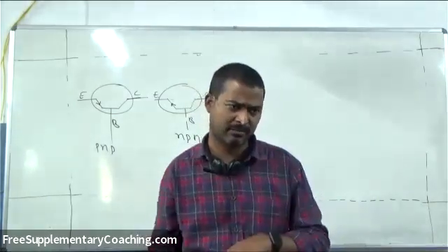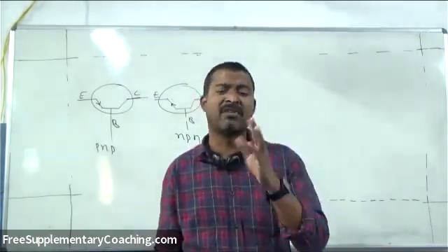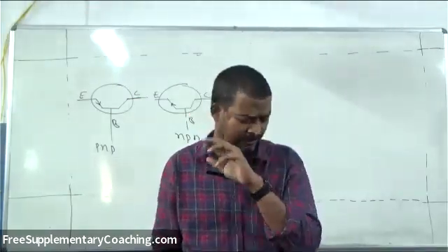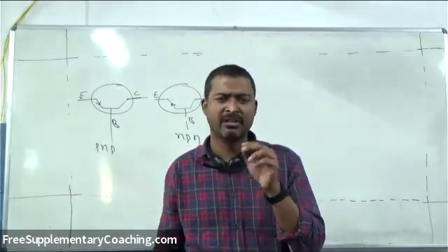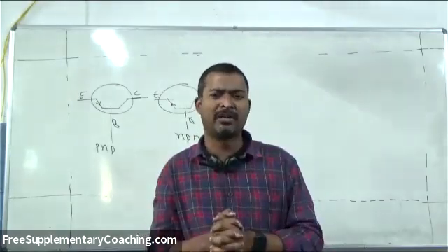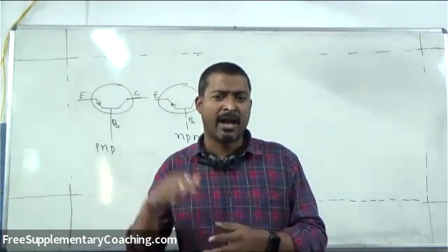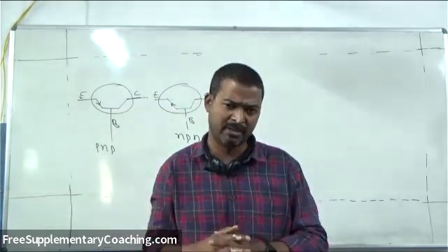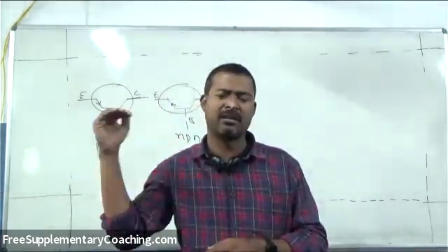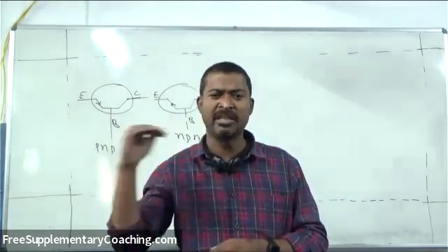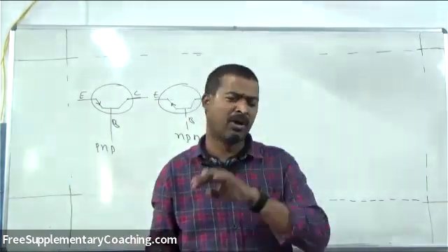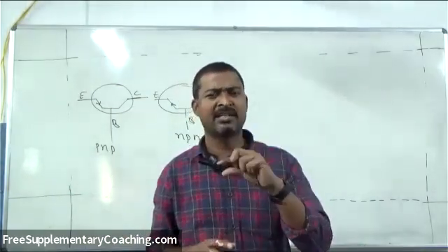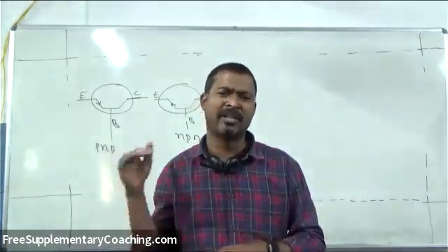That's it. Similarly, how does it convert into a voltmeter? Same, but a little bit of change in the definition. For the moving coil galvanometer, a high resistance resistor connected in series with the galvanometer converts it into a voltmeter. Low resistance connected parallel means ammeter. High resistance in series means voltmeter.